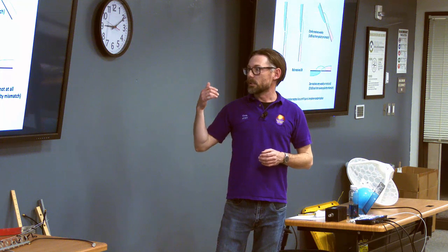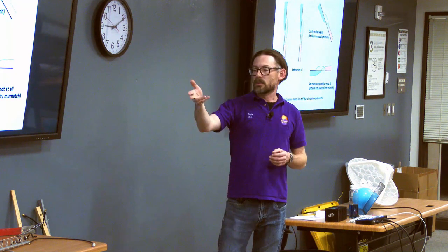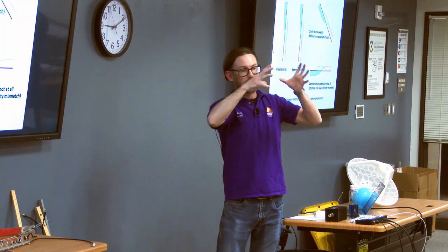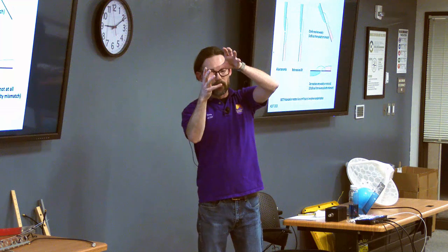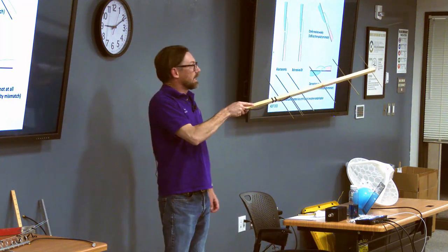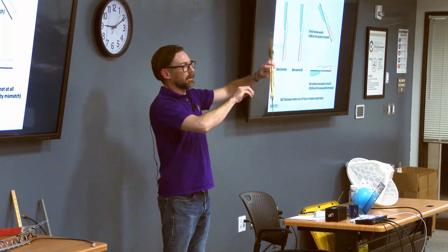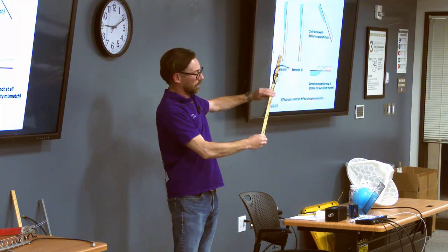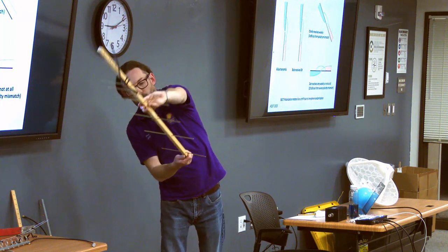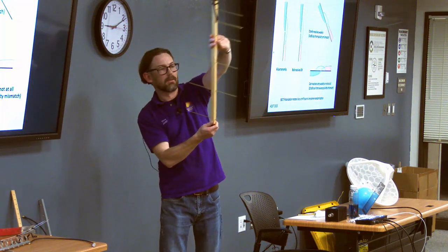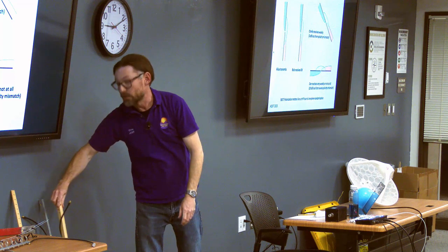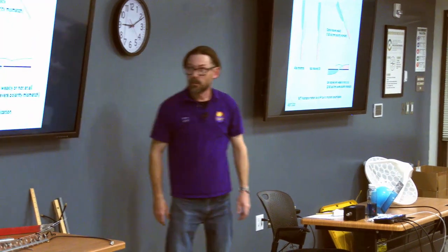It also means that, you talked about a satellite. If you're trying to talk to a satellite, well, those move through space. So your polarization of you with your Yagi pointed up and down, aimed at a satellite, well, that satellite could be tumbling in any direction. Even if it's not tumbling, as it goes from one horizon to the next, that can very much look to you on the ground like its polarization is changing. So circular polarization lets you hit all of those. And the atmosphere will naturally spin.